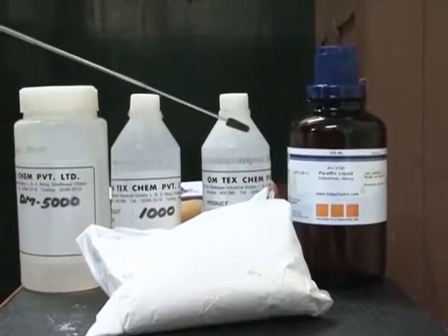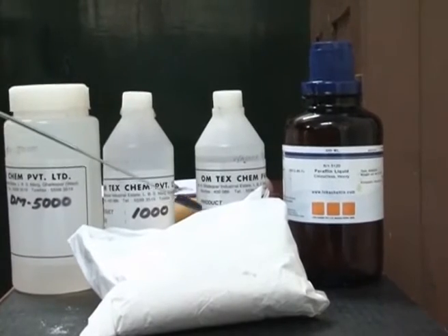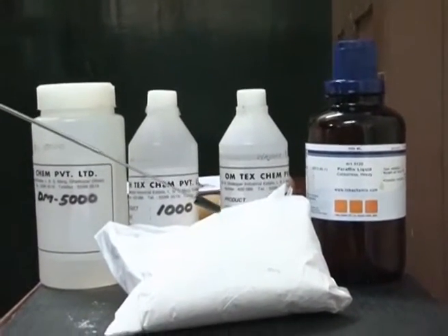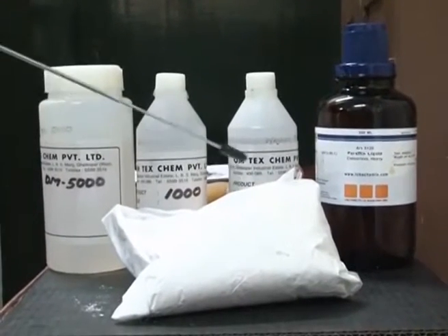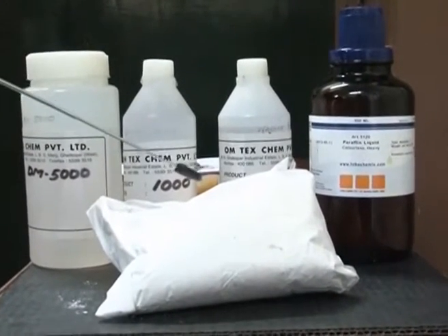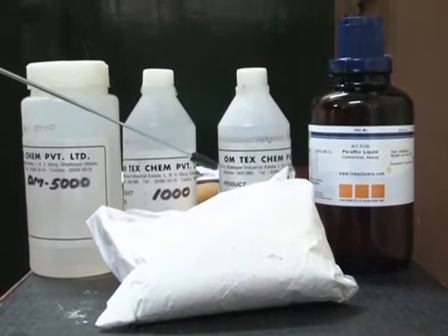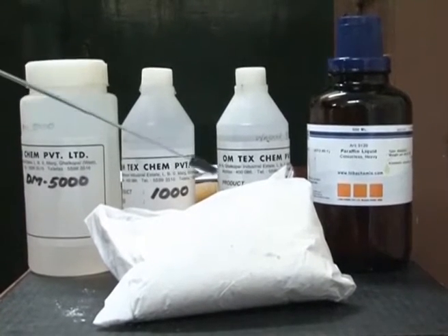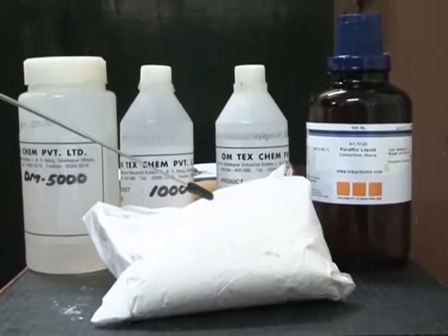Once these plasticizers and the softeners are embedded in the polymer chains, they spread apart and sit in between the polymer chains, and the polymer chains spread apart, so that it will provide the flexibility to the active abrasive grain.